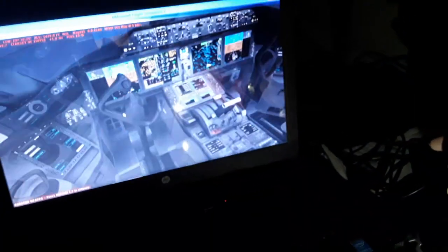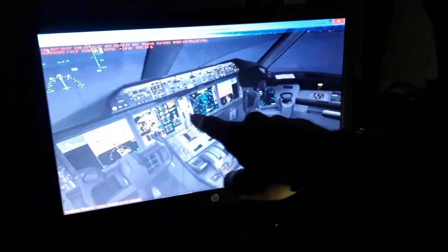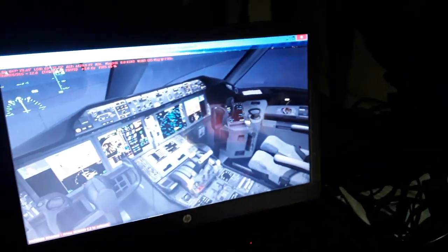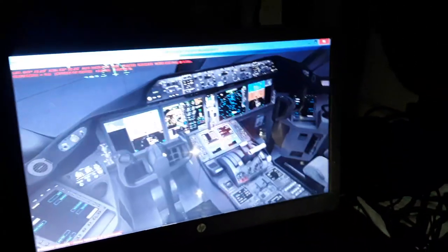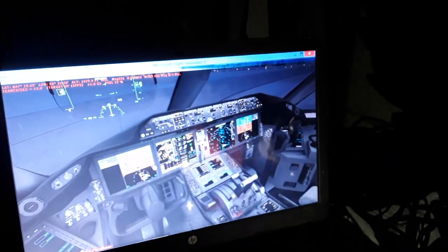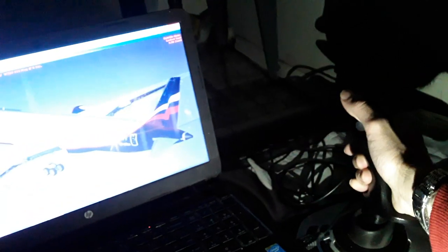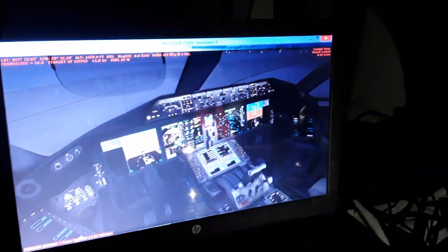When we move the flight controls, the thrust levers, thrust reversers, landing gear extend and retract, parking brakes, nose wheel steering, rudder, elevator, and horizontal trim stabilizer, all the flight controls of the aircraft are moved using hydraulics from the engines, compressors, and also pressurized air tanks. We also have bleed air from the bypass section.